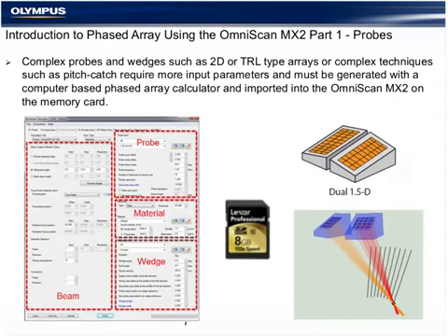In a more complicated probe, outside of the instrument, it requires a more complicated focal law calculator. The reason I included this slide in an introductory class is to demonstrate the point that all calculators from all manufacturers are basically divided up into 4 groups. 3 parts hardware, 1 part software. If you give the software all of the correct information for the probe, the material, and the wedge, you can then ask for the beam information.